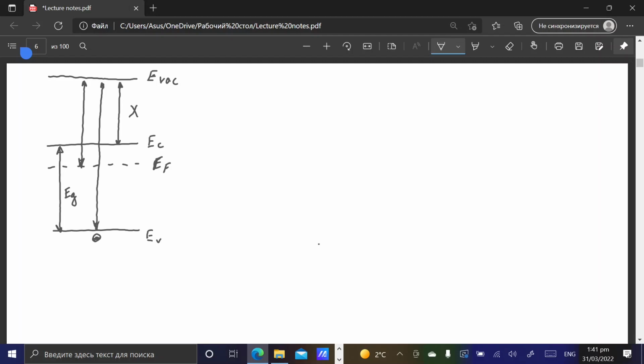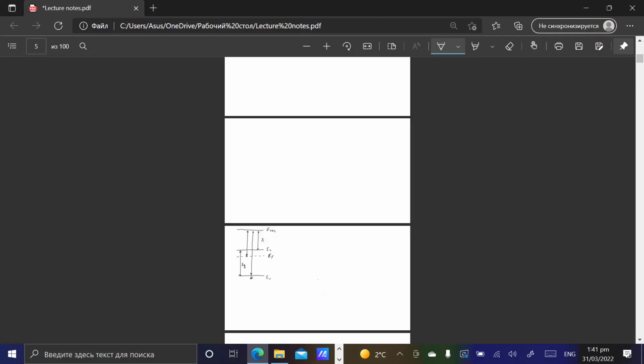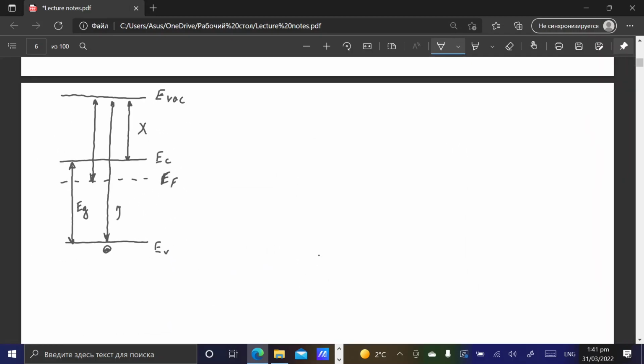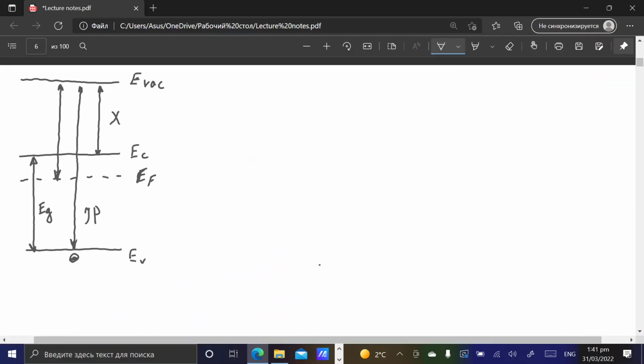However, this has a different name, so let's call this one ionization potential, and this is W, work function. So work function is the energy gap between Fermi energy and vacuum energy. So all these characteristics you need to remember, because you cannot make many steps further in semiconductor devices, so you definitely need to understand and remember these definitions.